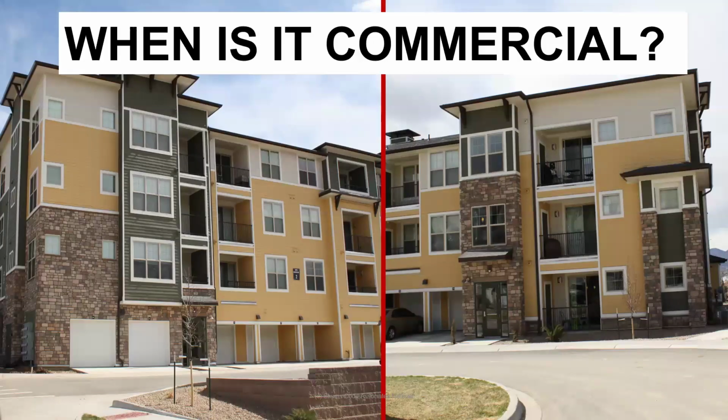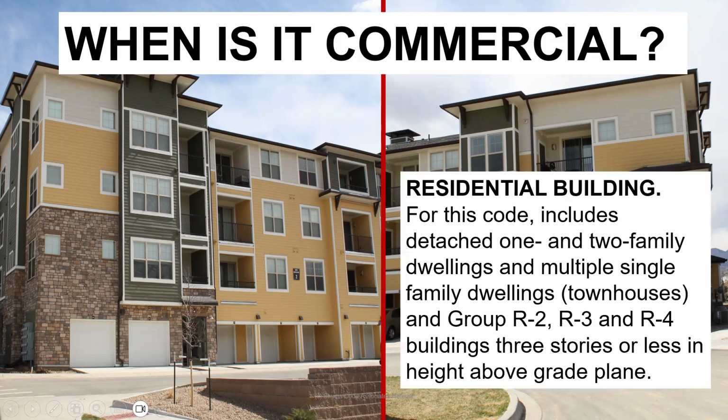So we're going to start by always making sure that we're following the scoping language of the energy code, and because we'll be talking about multifamily, this is really pertinent. We have a certain definition for residential building in the energy code that doesn't follow the specific guidelines of the IBC, right? So I can build an R2 that's 3 stories tall, and while I wouldn't be building that out of the IRC, I would still be using the residential application of the IECC for the requirements associated with that 3 story or less.